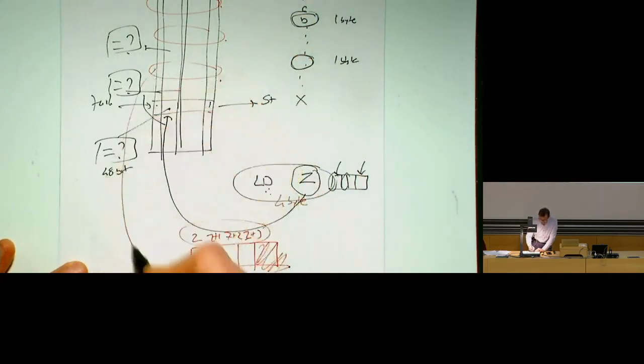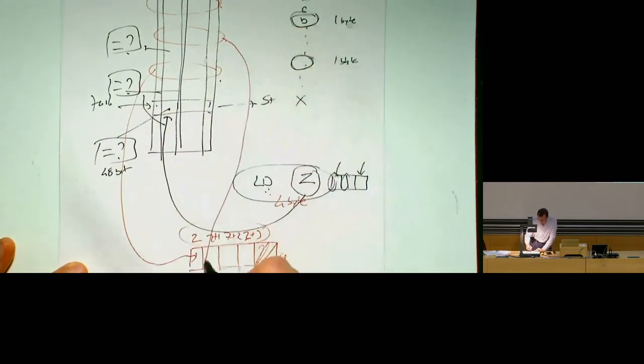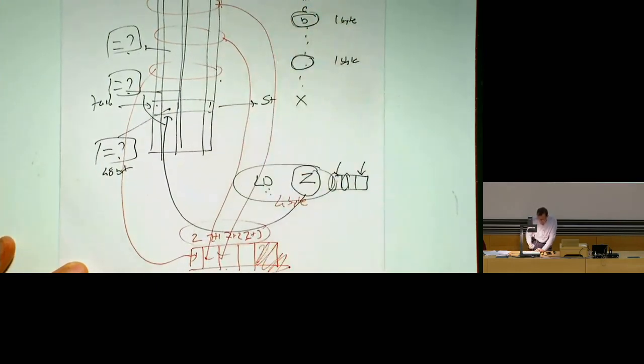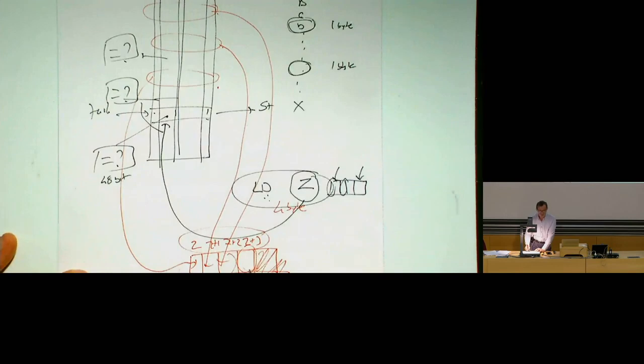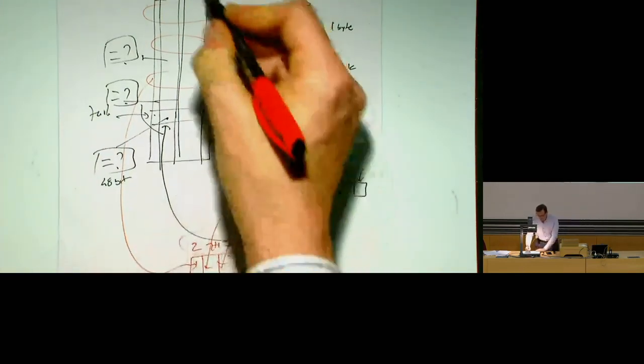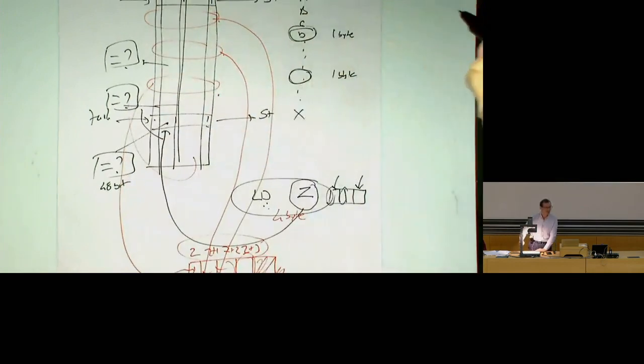Now, you may be able to find one that's writing here, another that's writing here, another that's writing here. Okay, 3 stores are writing here. Where do you get the 4th one from? Well, now you need to access memory for that, because there's no store in the queue that's writing to that one. So to be able to get your data value, you need to search this, and you also need to access memory. That's why this is one of the most complicated parts.